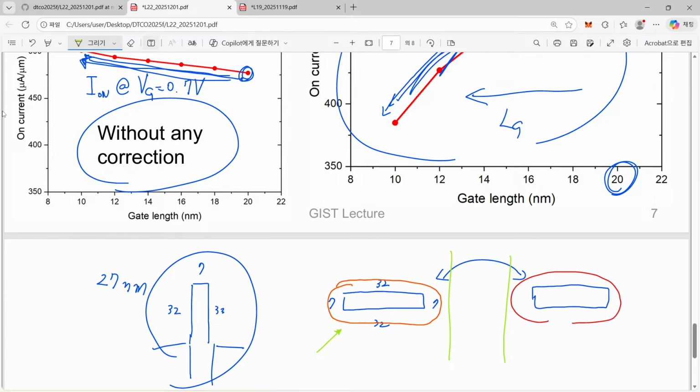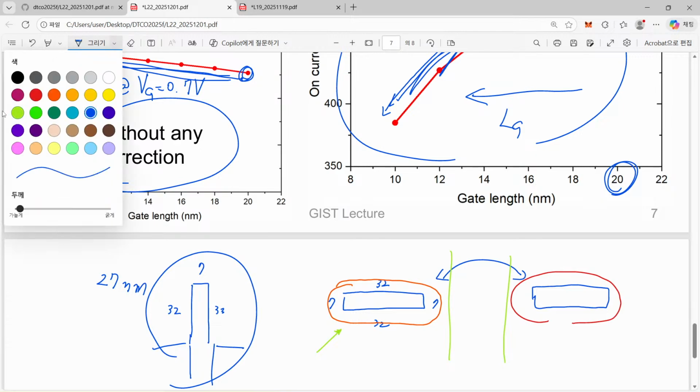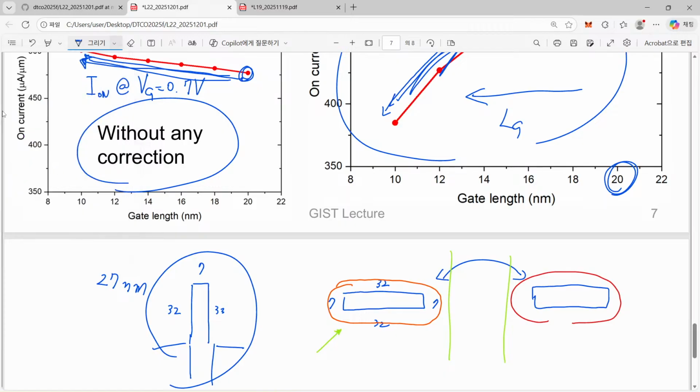Actually, that's the reason why in our current implementation we do not introduce this single stack transistor, in order to compensate for the obvious disadvantages in our area consumption. So we introduce more stacks. Although it consumes quite a large area, it has multiple copies of silicon stacks, so that can increase the drivability. So that is the one.